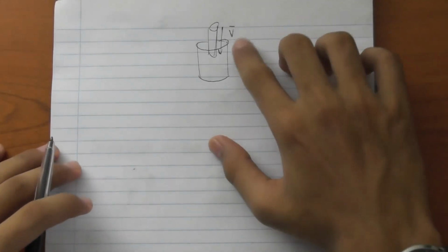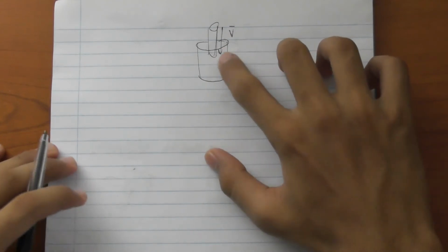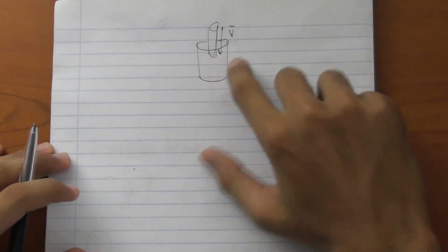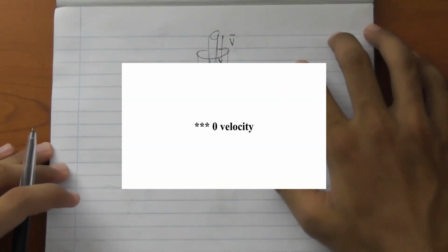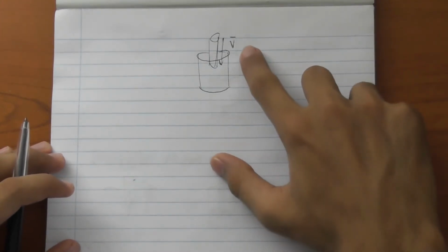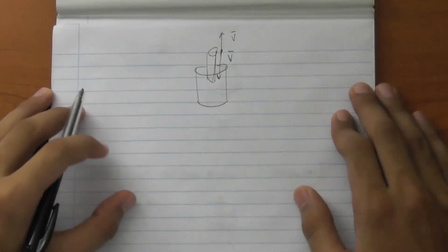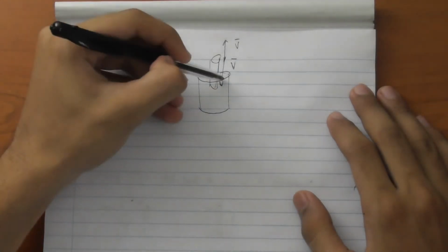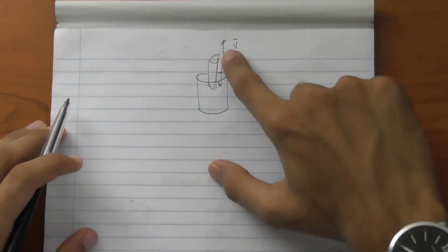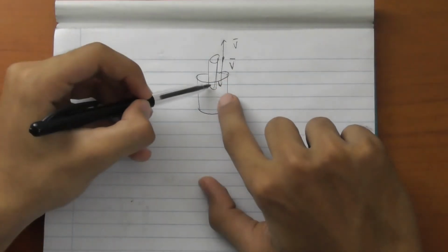So you have something that was initially moving down at velocity v. Because you want the value of the velocity relative to the rod, which has a velocity v, you're going to assume that the rod is constant velocity. Now the only way this rod is at constant velocity is if you add to this velocity v in the upwards direction. That would ultimately cancel out the velocity vector going down. Okay, so if you add a velocity of magnitude v going upwards, this is now stationary.